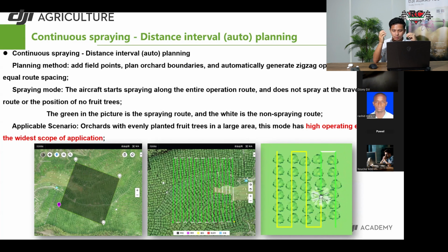Okay, we have two drones, so we will decide how many trees each takes, and which spot you take off from, which spot I will take off from. So that is your consideration. You have to select the takeoff points. From one takeoff point should be left and right, because as we all know, time is very important. Every 1 hour, normally for fruit tree, in liters, in 1 hour we normally do 7 flights. So how do we effectively manage? Otherwise, if you move from one place to another again and again, it's wasting time. So we want to finish in one spot as much as we can. That's how we have to manage the plan.